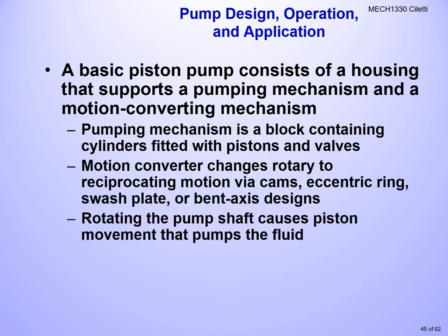Okay, but going through the piston pumps again, I've already shown you some animations, and we'll probably see some more here. It's a pumping mechanism, and it extends and retracts, and I'll show you the cylinder in class. As we extend and retract, we're filling up the chamber and then exhausting everything out of the chamber. And if we have the other ones, I'm going to pass around the swash plate so you can see that design as it rotates around.